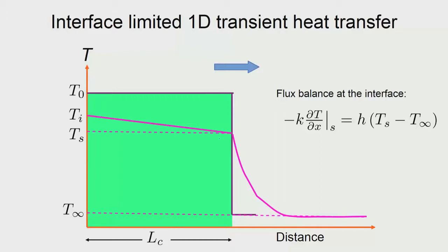you have got a small gradient, and the heat loss is in this direction. Whatever heat flux is arriving at the interface should leave. What comes here should leave, so they both must be equal for a flux balance, because there is nothing special happening at the interface. The heat flux that comes up to the interface is given by the Fourier heat conduction equation, and what is lost is given by Newton's law, and that is given here. The cross sectional area A cancels out on both sides